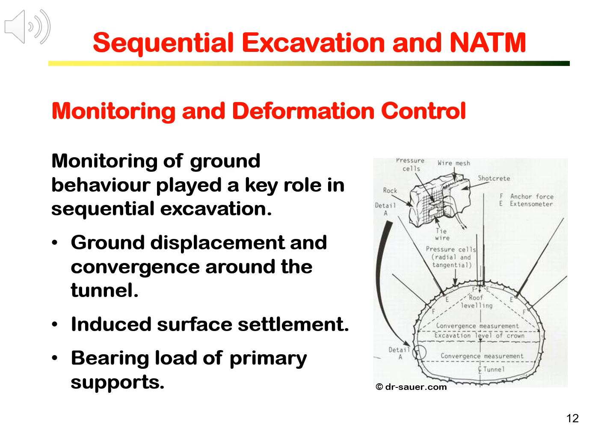Some of the common instrumentation and monitoring techniques are shown in the drawing on the right. We will in fact cover more details on instrumentation and monitoring in a later session. Observation and monitoring is to ensure the support is sufficient and the deformation is under control during the excavation, as outlined in the ground support interaction analysis.